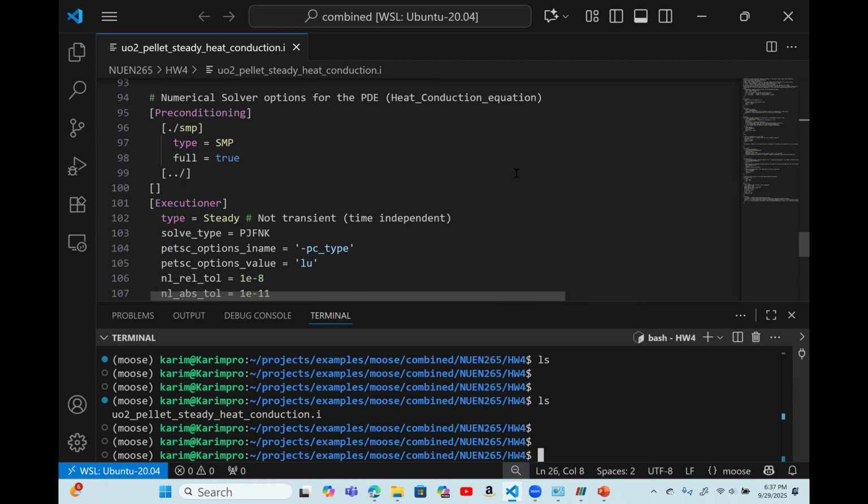So we don't solve it over an infinite number of points, we only solve it for a finite domain, and through the discretization, we transform the differential equation into multiple algebraic equations representing the solution at each point.